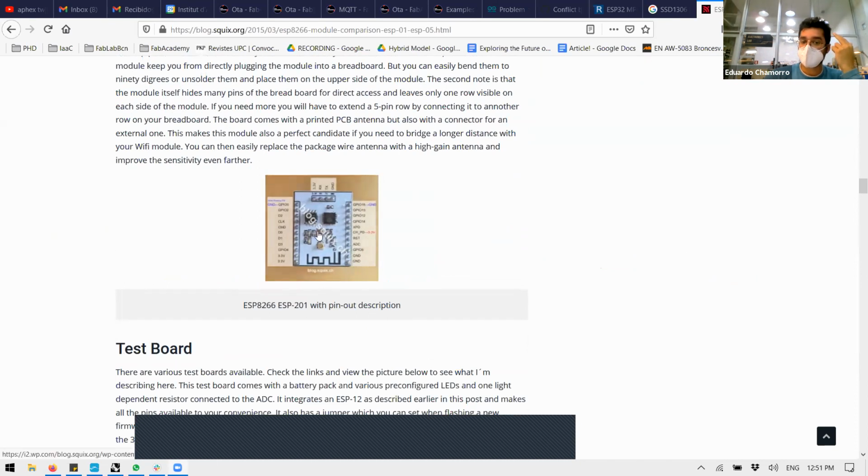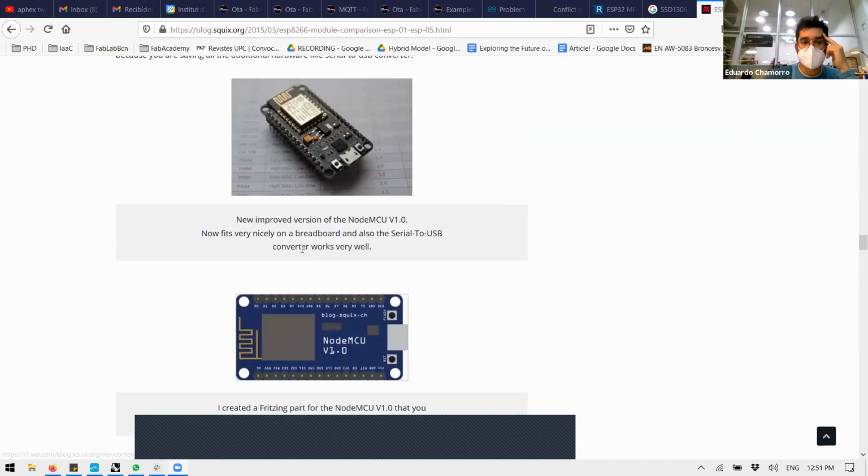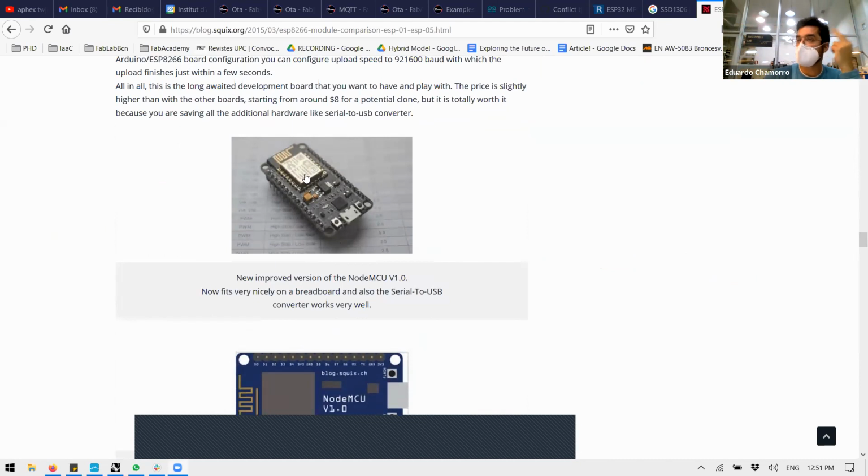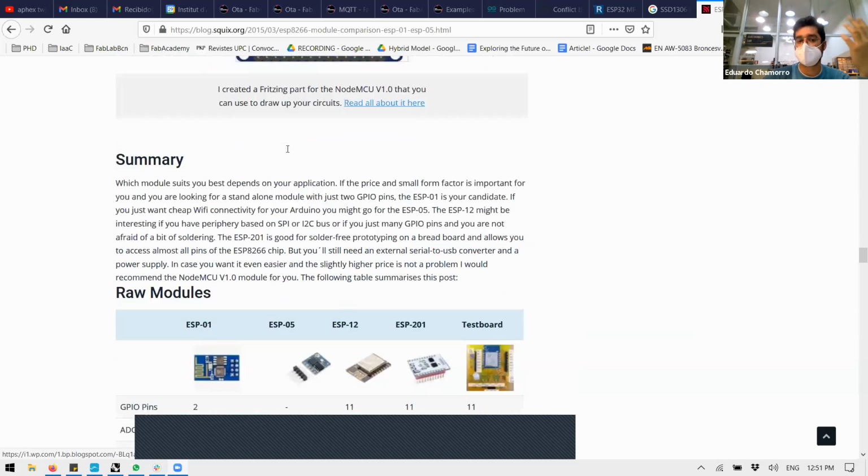In this case, it's exactly the same. It's an open one. In the case of the ESP, the microcontroller is at the same time the RF TX model. So they don't have two. This one does everything. Then you have other ones that, for example, this one has already a shielded metal plate that insulates the board. And what is the only part that is exposed? The antenna. That is a PCB antenna. Let's go later on PCB antenna designs.